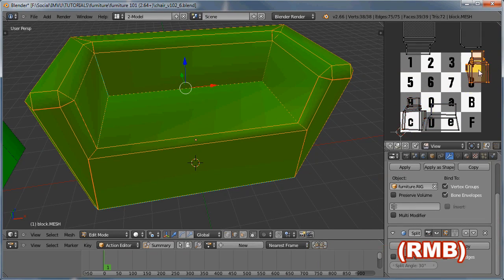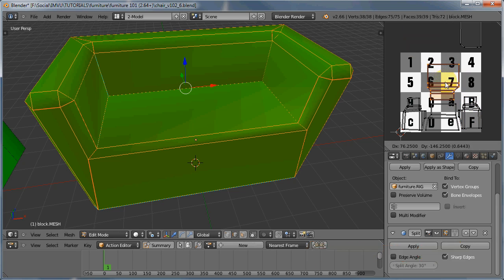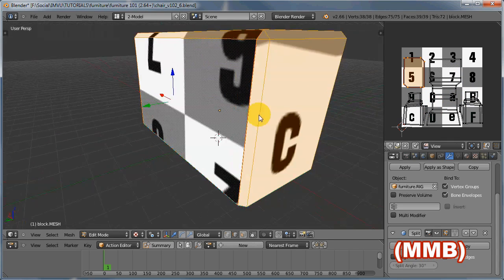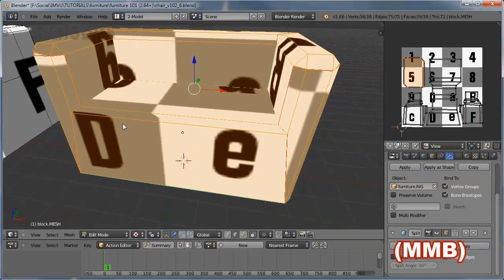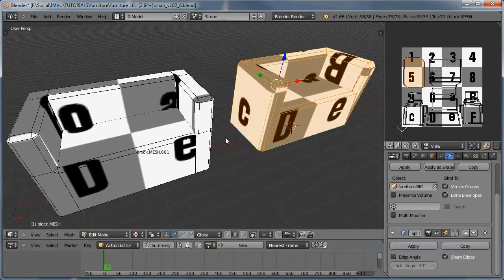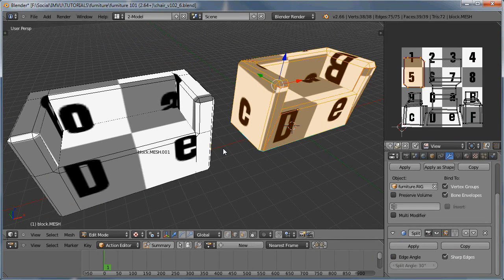Position the arms to either side of the seat area and the back just above, and the base can be placed anywhere where it will fit. Then change shading, and there we have the second chair with the UV map all cleaned and tidied up. So you can see there are advantages and disadvantages to using either or technique to round or soften the edges, and what consequences that has on the UV maps.